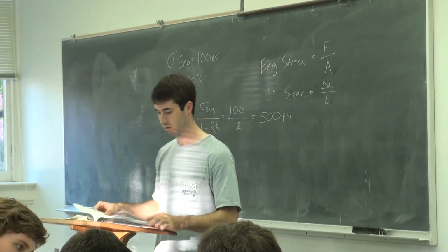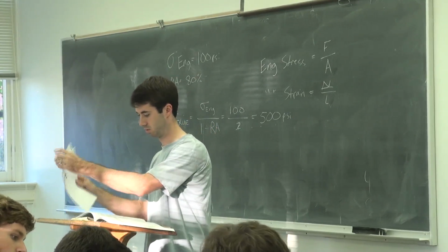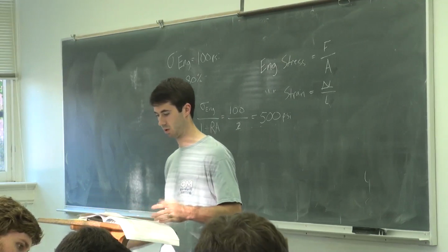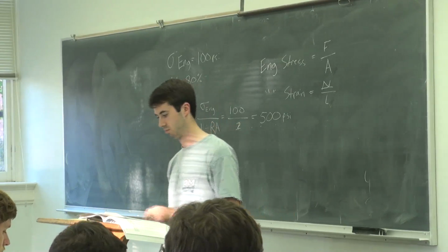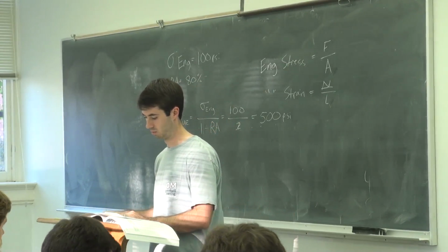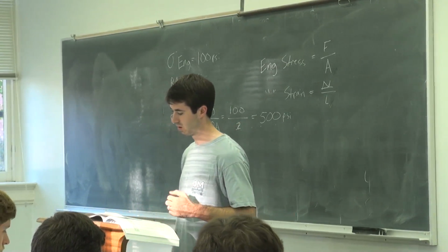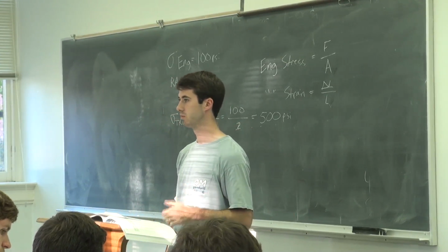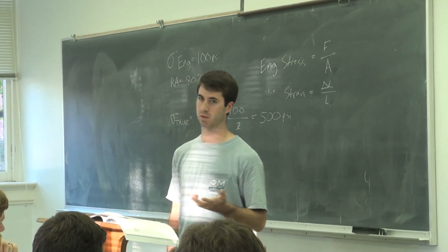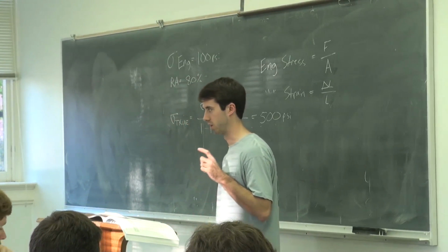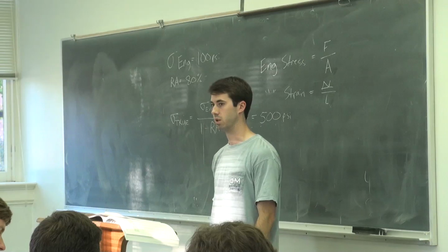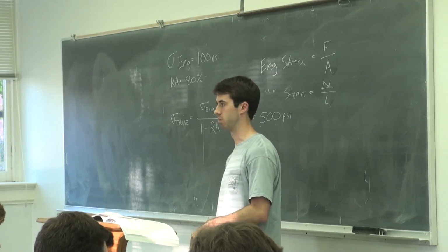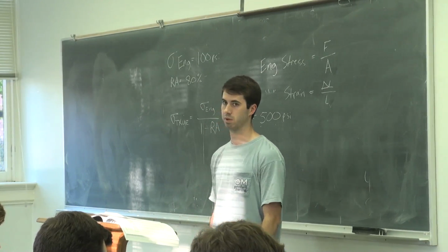They got the equation and nothing else. Now, I guess since I am a materials guy, we'll break it down a little more. You remember what the structural number is? It's basically the capacity of whatever that structure is. So you need a certain structural number to protect your subgrade for whatever traffic conditions, environmental conditions, or whatever you've got.